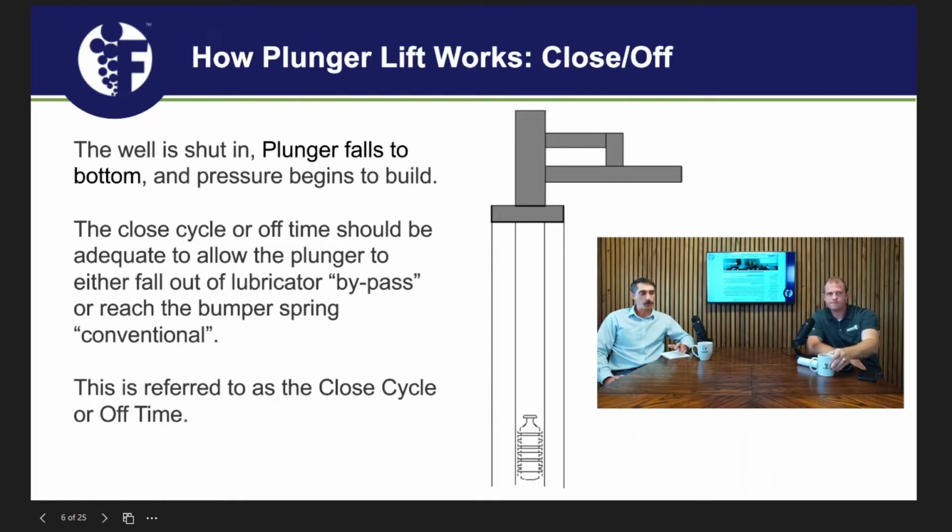Typically, historically, it's been a motor valve, Kimray or something else. And that's usually over here on your flow line, downstream of the wellhead. Correct. Right? Correct. Even just a few feet though. Okay. Typically. And so what we're doing is we're using our electronic device to close that actuator and just shut the well in. And then just due to gravity, the plunger falls.